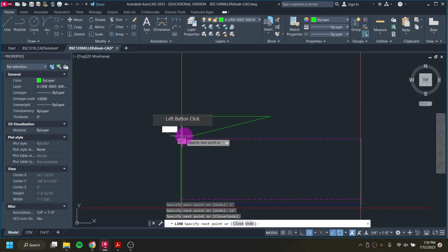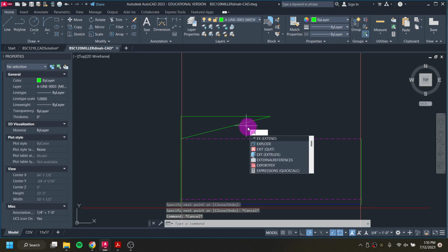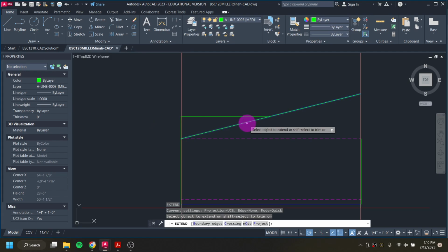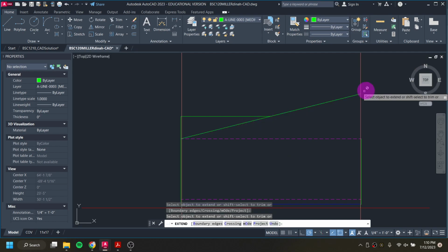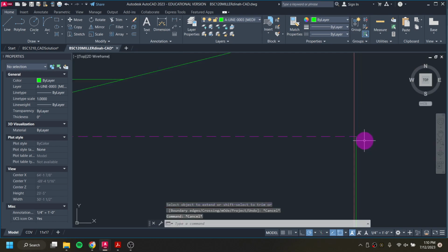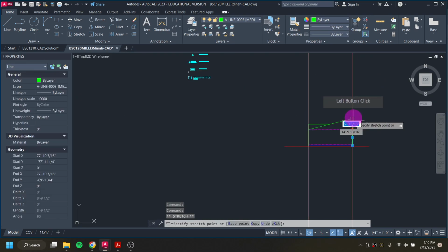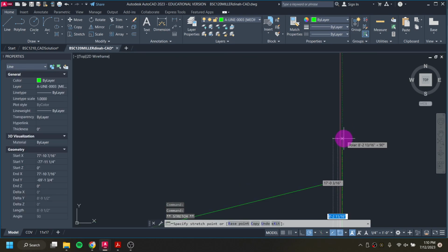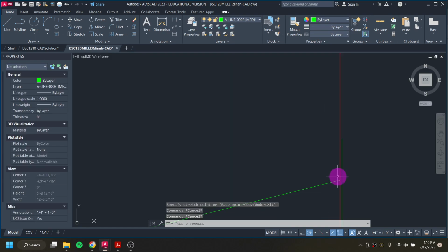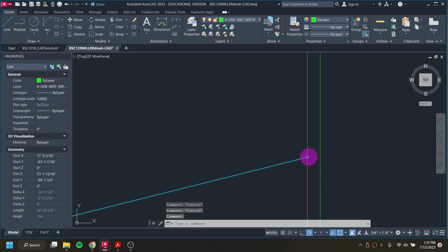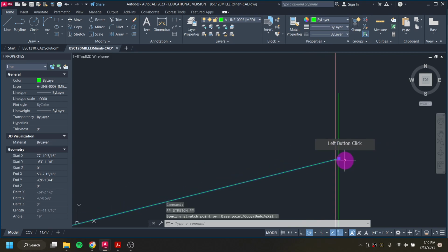I can connect those dots, hit escape to end the command, and use the extend tool, EX, to figure out where this is going to meet here, and then hit escape. I can click on this grip to bring it really far up, further than I need, hit escape, and I could even click on this line, and as long as I'm getting that polar tracking, that green dashed line, I can figure out where the two of those would meet.